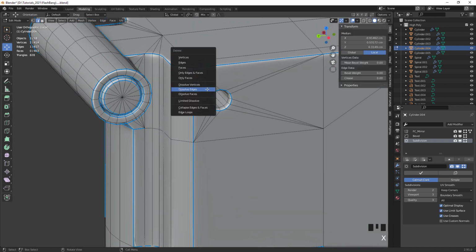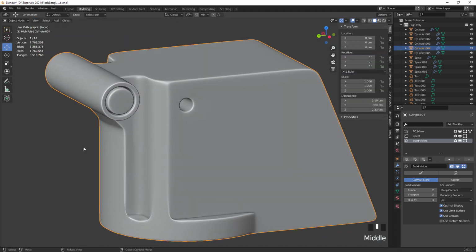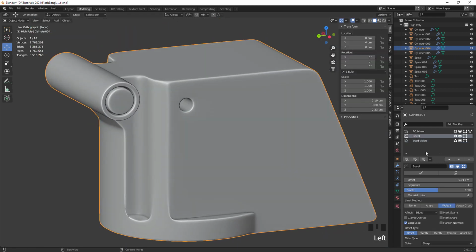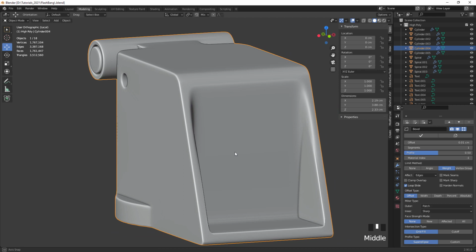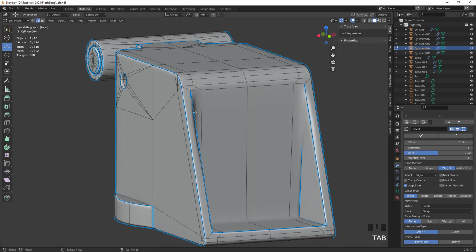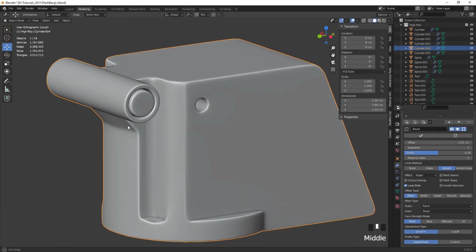And here I'm gonna dissolve this edge because it causes some weird artifact otherwise. Let's go in the bevel settings, and I wanna change that over here to patch for the outer miter type. And then we have some extra edges here that require some bevel weight to get rid of this overlapping.